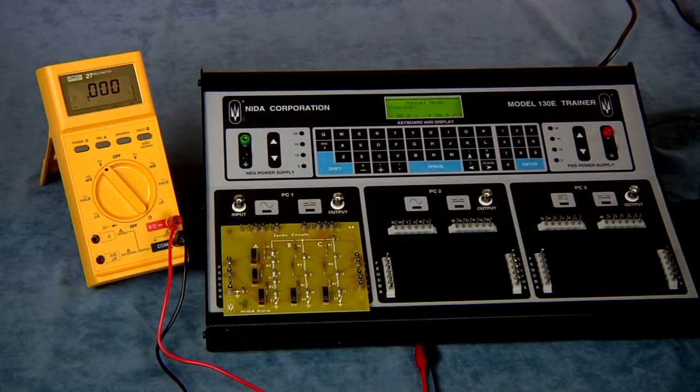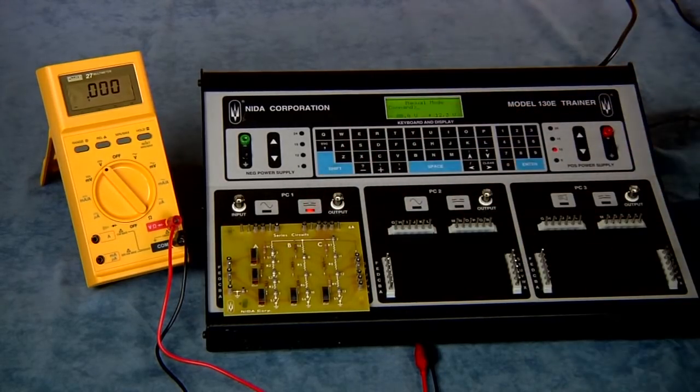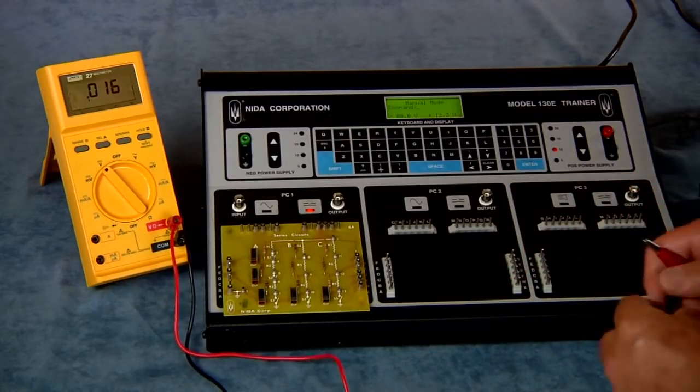So to start the experiment off, we're going to turn the power supply to 12 volts, and that's what it said in the documentation. So there's 5 volts, there's 12 volts. And then we're going to need to apply that power supply to the PC1 position. And again, we'll need to use the DC switch for that. So now we've got the voltages applied. Now, I'll go ahead and make those measurements across each of those 3 resistors so we can see exactly what's there without having any trouble inserted into the machine, as it's told us in the procedure steps.